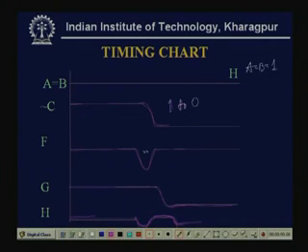See here, F we are calling this a static hazard. Now with this hazard, for this particular circuit, when we have included another inverter and the AND gate, then we are getting some more added glitch. See this one for the H, this is some more for this. This is called the dynamic hazards.